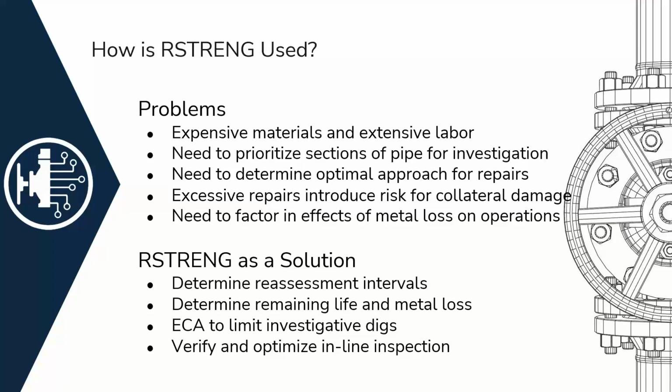This is the key. You get a smart pig run, and what's the first thing you need to do? Do you trust everything that the pig run has done? Remember, it's plus or minus. It's 80% accurate, plus or minus 10% of 80% of the time.